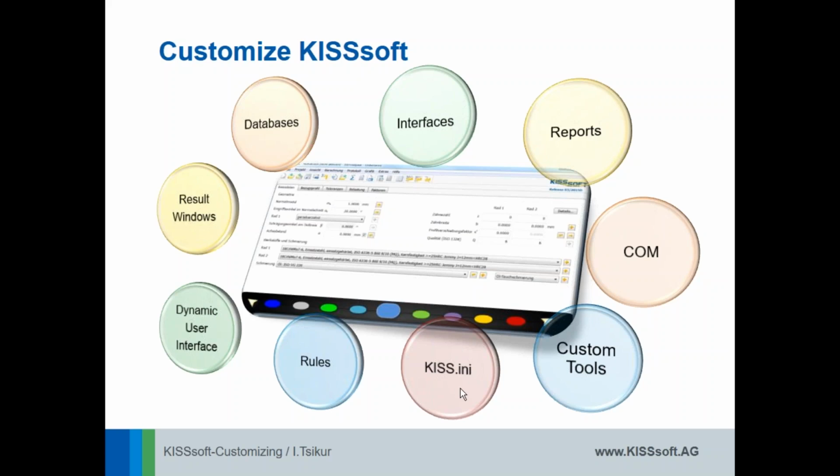Then we're going to speak about the initial settings. In KISSsoft, initial settings, what do we mean by that? It is when you start KISSsoft, you might want to pre-select English as your standard language, or, for example, you could even create log files. What is a log file? I have several inquiries from customers, especially from IT, asking, is there a way to manage who is using the license and when, to generate such a report, especially to see who is using which calculation modules? This is possible in the initial settings, and I'm going to show it as well in this presentation.